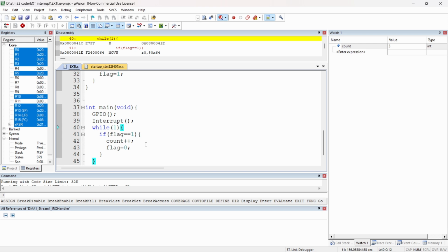Consider this scenario: the ADC is reading the temperature value using the temperature sensor which is connected to the engine. When this temperature exceeds a predefined value, which we will consider as 60 degrees Celsius, then the ADC will give the interrupt.